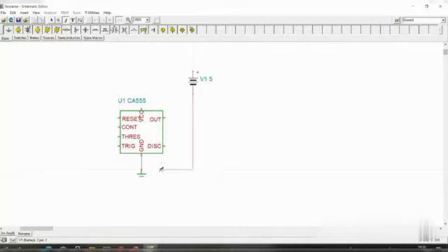The positive point of that 5 volt should be connected to VCC. So that is over. Initially, whenever you are dragging and dropping an IC, the first step is to give that IC the supply. Otherwise, you may forget, then the IC will not work. So for this IC, plus 5 volt we have given. That is the first step.